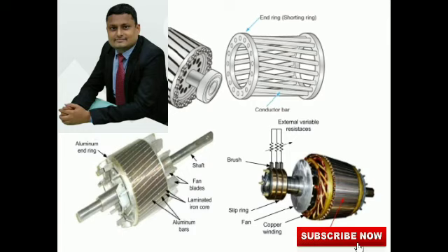Now, hence optimum length of air gap is necessary. So what will be the optimum length of air gap? Lg equals 0.2 into 2 root under DL mm. D and L dimension to be put in meter. So outer diameter of rotor Dr equals D minus 2 into Lg. So you can get the value and put in this equation.